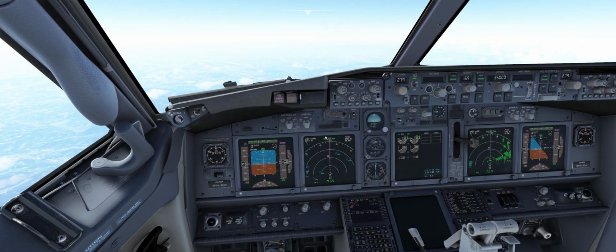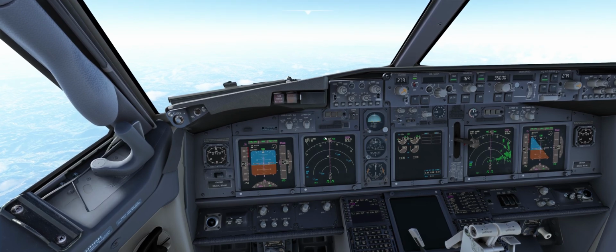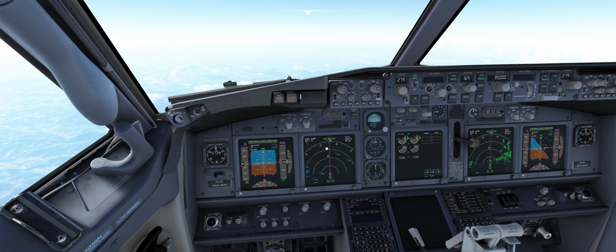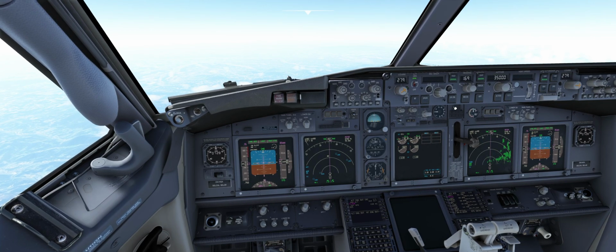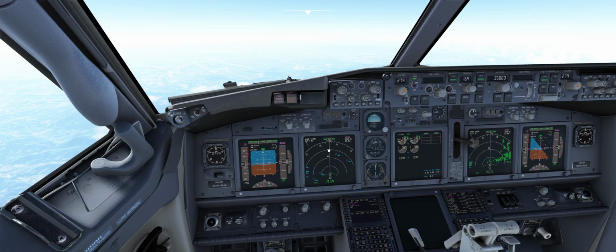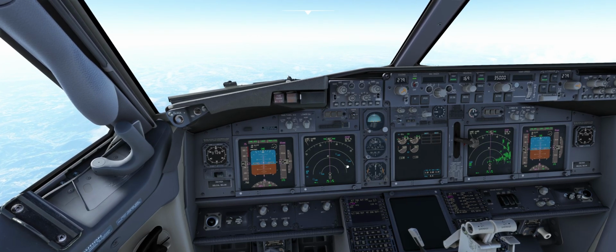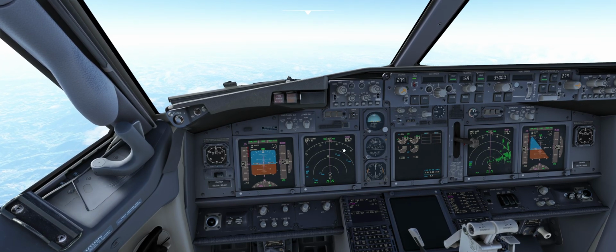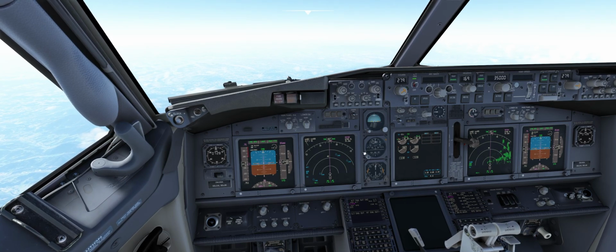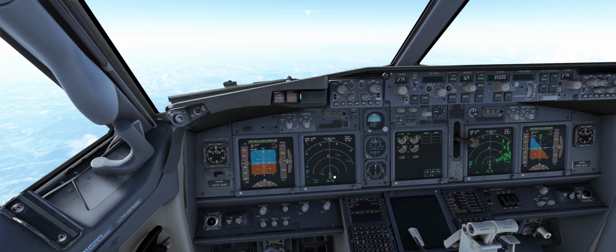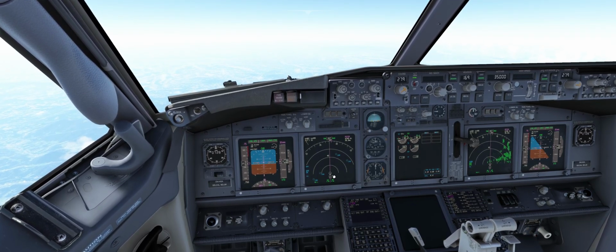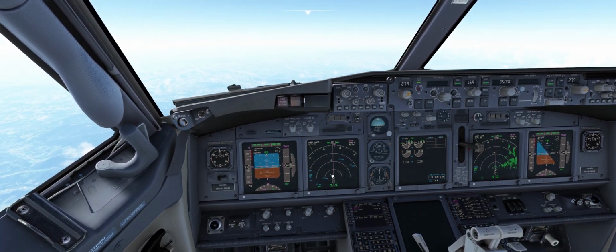Now I will stop talking and tell you something. Many pilots use heading select. I suggest, if you are going straight, with no turns, basically keep it in LNAV mode, because the air traffic controller knows that you are proceeding via the flight plan route and not with heading select.